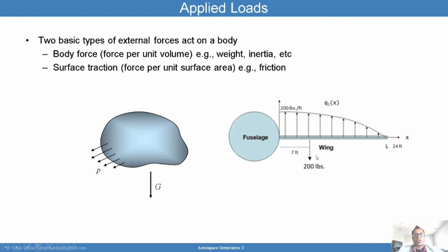But surface tractions are forces that are acting on the surface. If you think about it, there's no possible way you can apply a force inside the body other than body forces. You can only apply surface conditions, surface loads on the structure. Point loads are actually not even possible. But we can represent point loads by applying a small traction on a very small area.